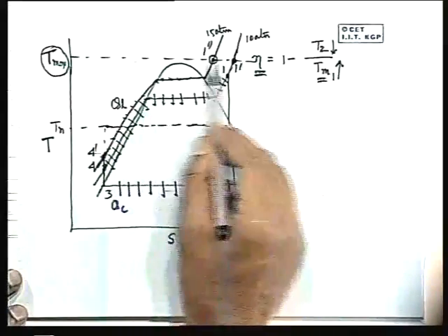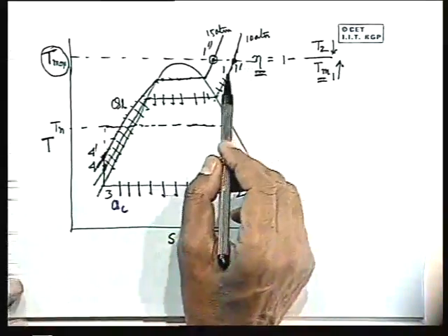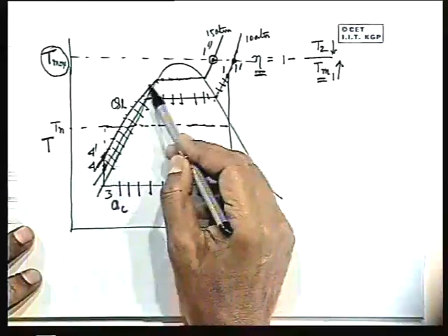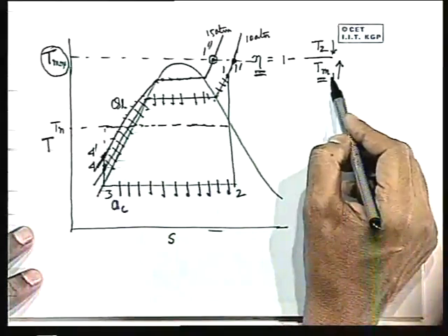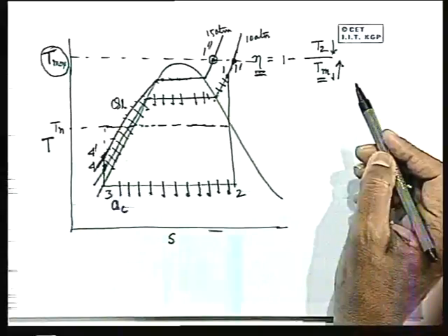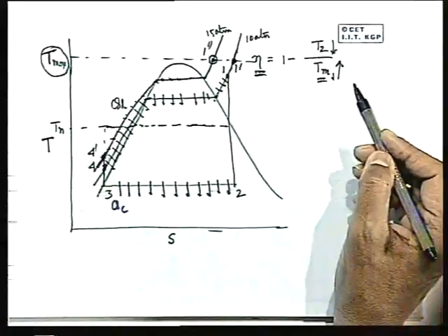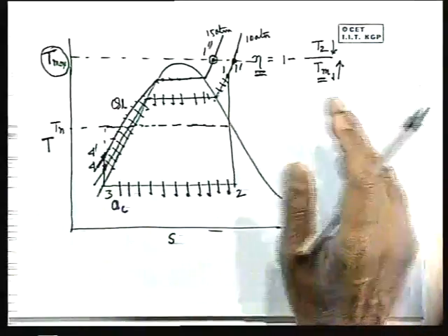That means setting the same maximum temperature, because of the metallurgical restriction, I can increase the boiler pressure and I can increase the Tm1. But where does the limit come now? By increasing the boiler pressure there has to be a limit again. Everywhere you see we cannot monotonically go on increasing an operating parameter to gain efficiency. So there is a point where you have to stop.